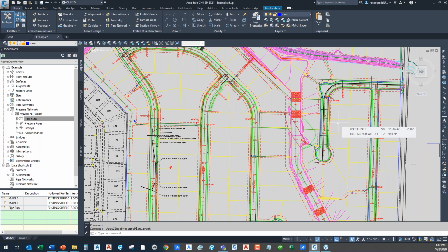Then we can do bridge design and rail design and extensive presentation and sizing and so on in Infraworks, particularly the bridge design, right? And then we can actually export from Infraworks to Revit to finalize the bridge design, do all the detail and the construction documents. Then any changes and modification can be pushed back to Infraworks and then back into Civil 3D. So it kind of creates this round trip functionality, right?